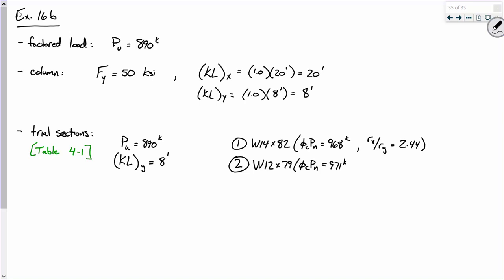Do you see that? You were looking at 20. Well, that's why. Again, on the left side of that table, it says effective length with respect to the least radius of gyration, in this case Ry. Now, in order to check this, we're going to need Rx over Ry. So what is that? 1 point... All right.